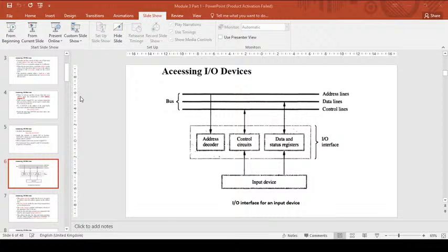The next part of the code is WAITD Testbit #1, STATUS. Now one character is read, and it has to be displayed using the display device. To display, the processor has to check whether the SOUT flag is equal to 1. If SOUT is 1, that means the display device is ready to display.